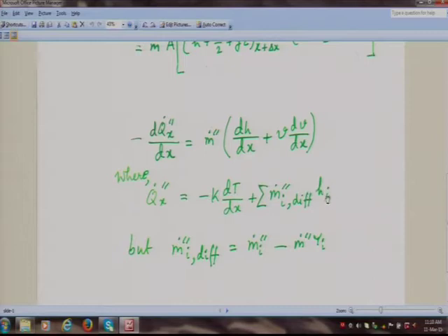See, the question that he is asking is: is h dependent on temperature? Of course, it is dependent on temperature, but then what is the temperature he is asking? That temperature is the temperature at that particular x. So, q dot x double prime is a heat flux value at a particular x. At that x there is a temperature, and that temperature will determine the value of h i. So, h i depends on the particular species that we are talking about, and it also depends on the temperature locally.